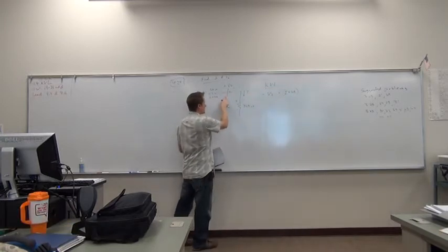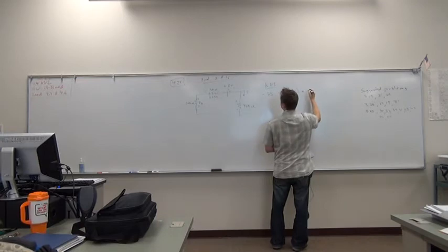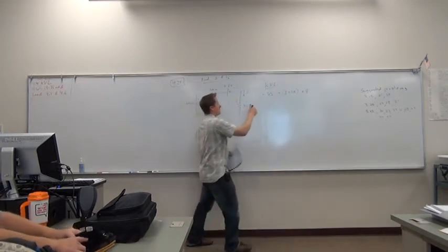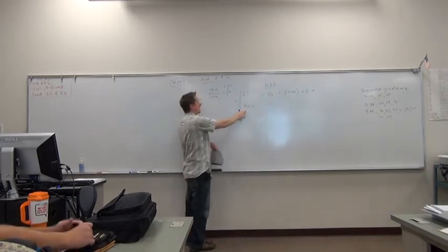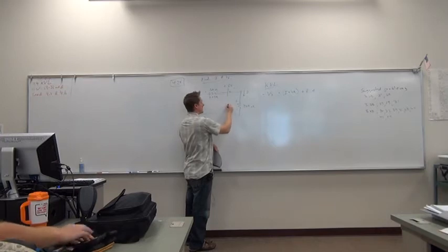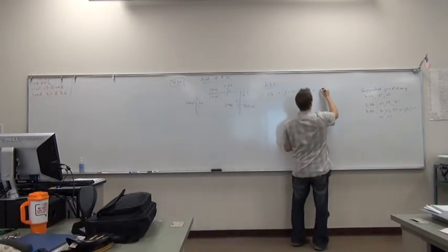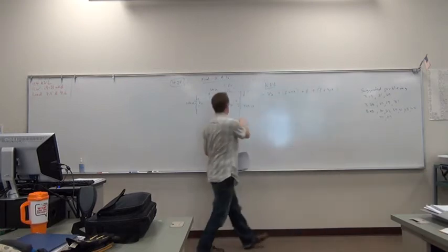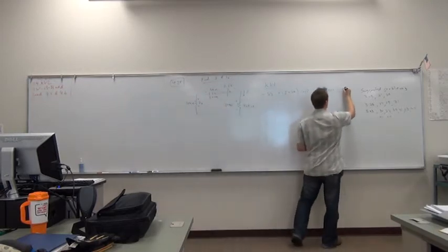We go through this. What do we assign? We're going through the plus, right? So it goes plus 8. We continue to go through here. We hit a plus sign and we say plus. What's the voltage across this? I don't know, but I know that whatever it is, it has to be I times R. I times 40K. And then I continue to go around and I wind up at the same point I started. So I say equals 0.